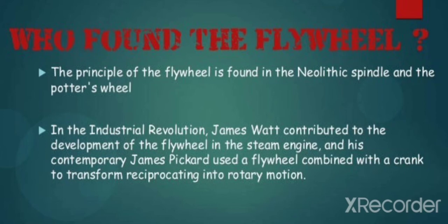As we all know, if we have constant load, then governor will remain idle, but due to cyclic fluctuations in energy, flywheel will always work. Governor has no influence on cyclic fluctuations in energy, whereas this flywheel has no influence on mean speed of engine. When the engine speed is at mean, this flywheel has no influence, whereas when there are cyclic fluctuations in energy, governor will have no influence.